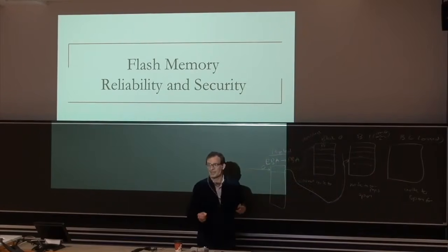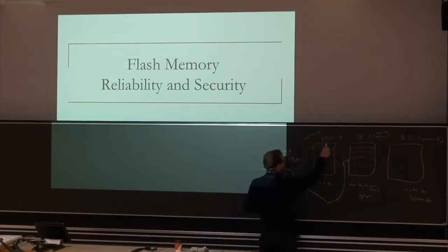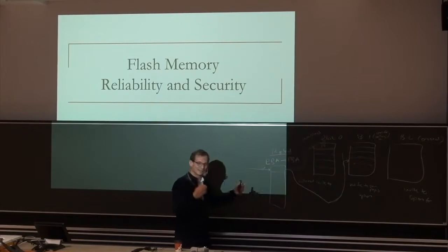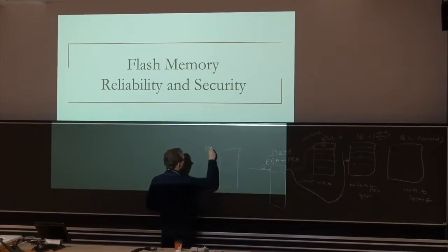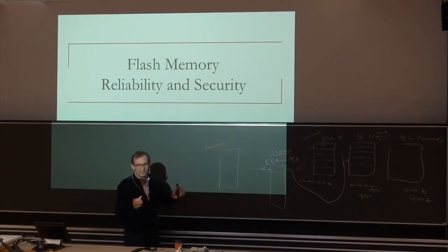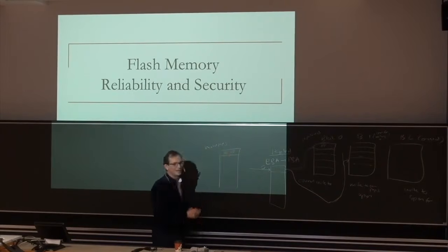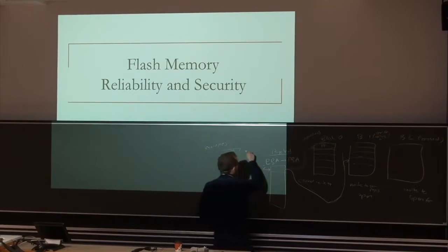But which also means that the flash translation layer needs to be aware of everything. Now what happened to this? That's obsolete. That's a stale value. So the flash translation layer actually keeps another table that says these are my invalid pages. I mean, this could be organized in different ways, of course. And this could be one linked list. So one of the invalid pages is block 0, page 0. I've written it somewhere else. So that's invalid.